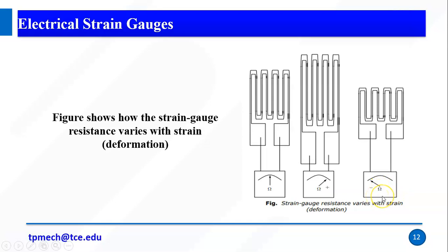So a strain gauge is like a strip. It is made of wires or foils or other types. We are going to place or paste the strip on the object on which we are going to measure strain. If the object gets tension, its cross section changes, so the gauge's cross section changes, and the resistance changes. So based on the resistance value we can measure the strain, right?